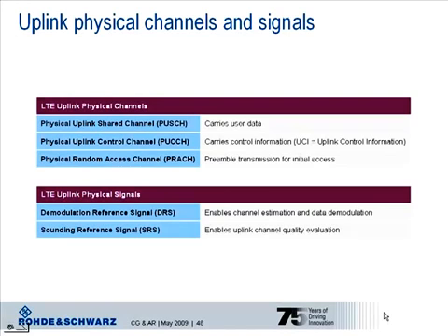The two types of physical signals are the demodulation reference signals, which are used by the eNode B for channel estimation and correct demodulation. Further, sounding reference signals are used by the eNode B to make scheduling decisions based on the channel quality.